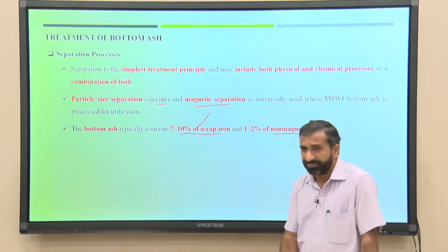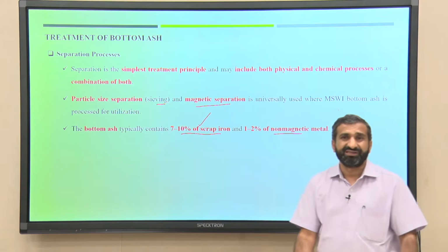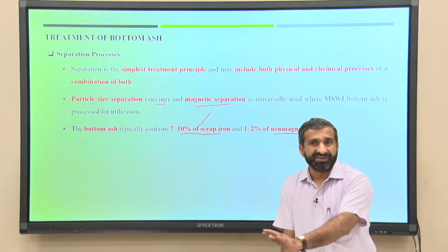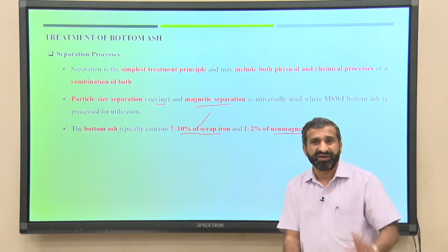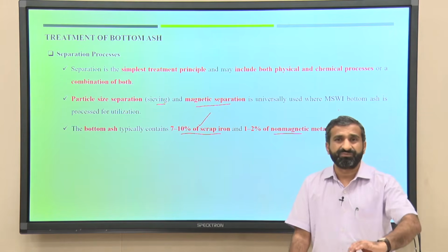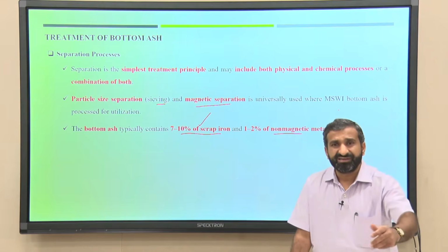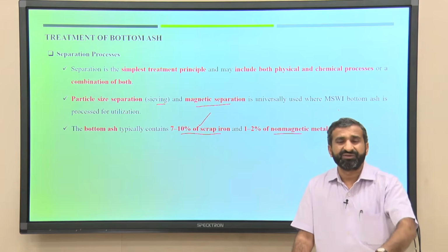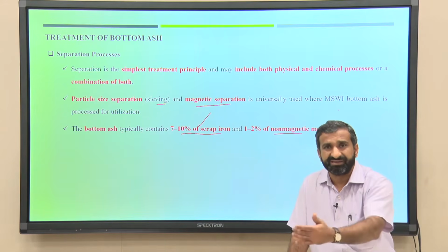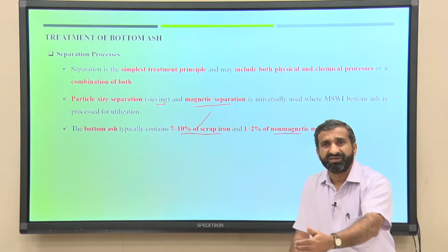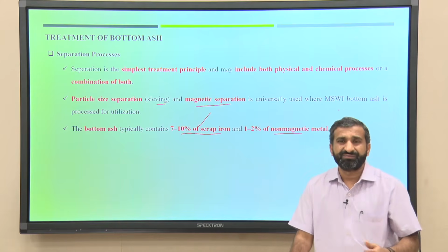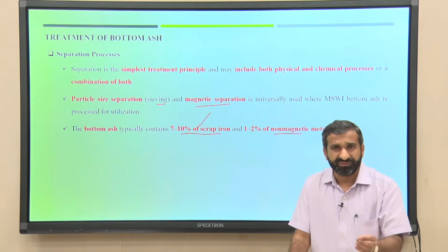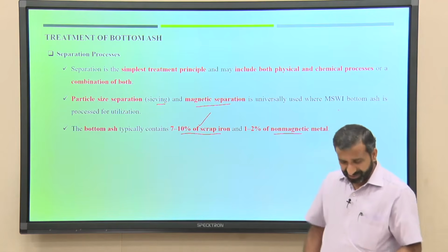Particle size separation is also an important unit, because different purposes require different particle sizes. Suppose you are planning to use these ashes as aggregate, the size will be different, and if you are trying to prepare brick or mix into clay soil to produce fired brick, the size requirement is different; you will require very fine particles for such purposes.